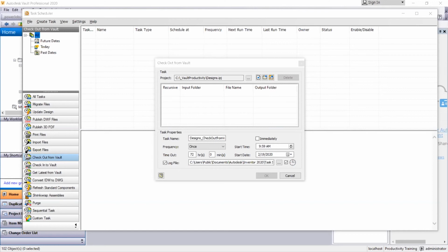Yeah, so there's a question here coming in. Can we use Task Scheduler to upload files from our local machines into the Vault server? Yeah, so just like I did right there, it was on my local machine, and I was able to upload them into Vault using that project. Again, in this case, what I ended up doing is moving it to my working folder to upload into Vault to make sure that it's in the right location. If you are doing it off a network or don't want to move your whole assembly to your working folder, you can use the Autoloader to import that into Vault.